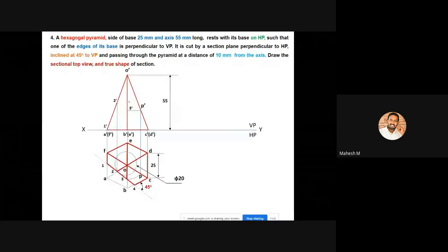Okay, no doubts. So the fourth point, where is the fourth point? It is available exactly at the line called B to C. So here we are having B dash and here we are having C dash. So you can project this fourth point up to the base. So this one can be marked with a notation called 4 dash. Now you got all the 4 cutting points in your front view.